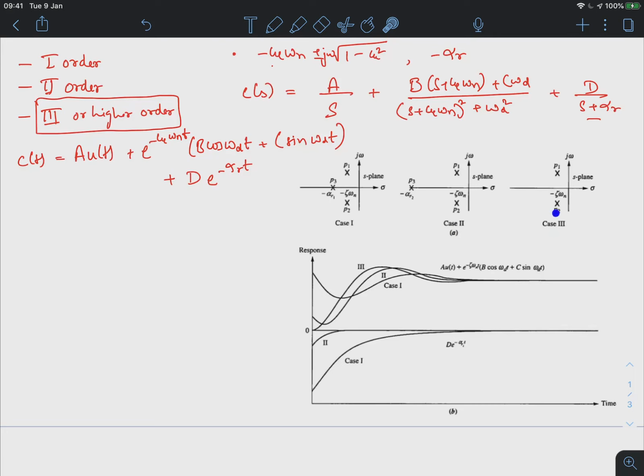We haven't changed those poles of the second order system, but what we are interested in is, if I add an additional pole on the real axis, how the location of this pole would impact the behavior of the system. So in the first case, alpha r1 is here, that is to say closer to the dominant poles. Here the dominant poles are the complex conjugate poles of the second order system.